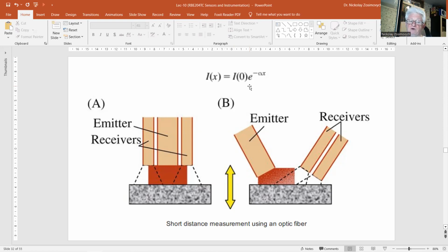The absorption coefficient of air is rather low. Some materials show a much larger absorption and can be used to create a distance sensor based on light attenuation. A design with a fluorescent optical fiber, very popular lately. A light source injects light into the fiber at a particular position along its line. The intensity of the light that arrives at both ends of the fiber is measured by 2 photodiodes.